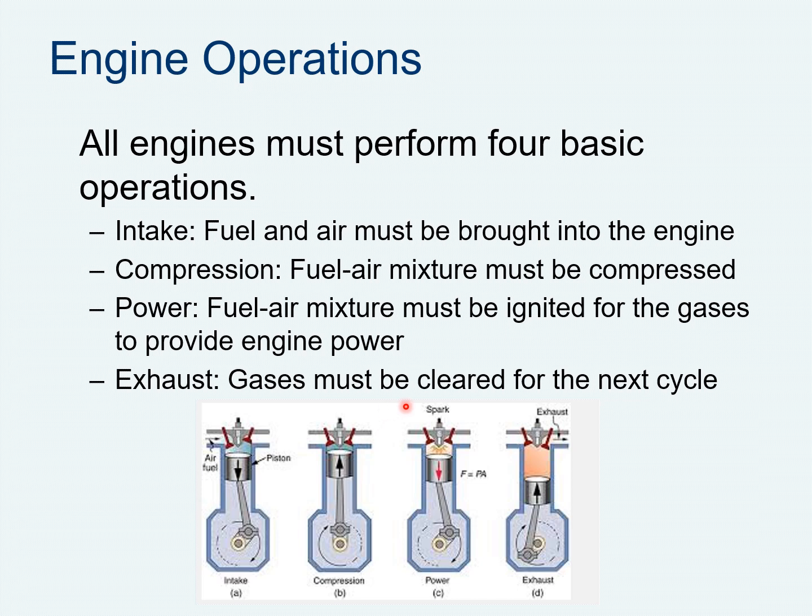Third one is the ignition stroke or power stroke, where we have the spark and both the valves are closed. When the spark appears, the fuel air mixture burns and tries to expand, which pushes the piston downward. The last one is the exhaust stroke, where the piston moves up, the exhaust valve opens, and the burned fuel air mixture goes out of the engine. This process goes on.